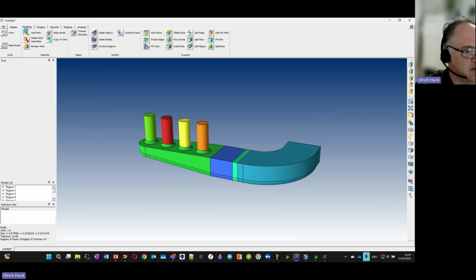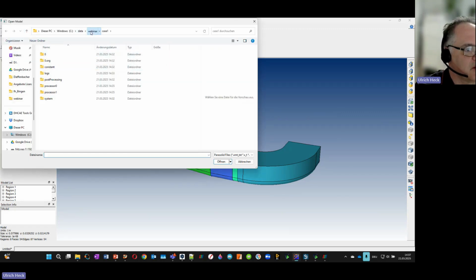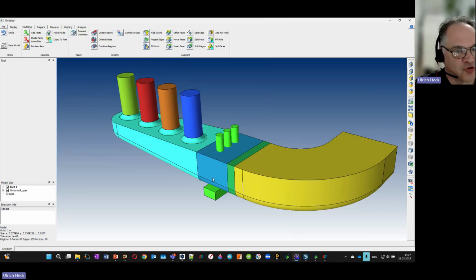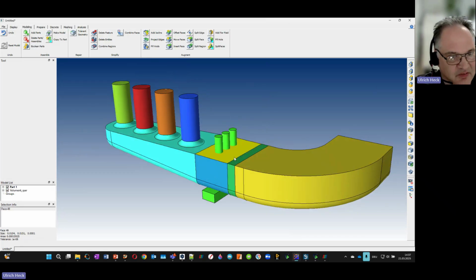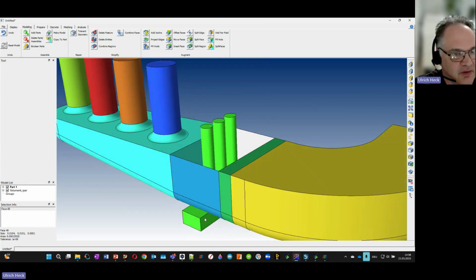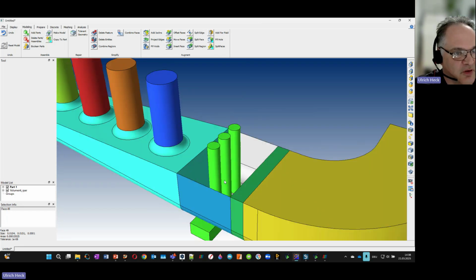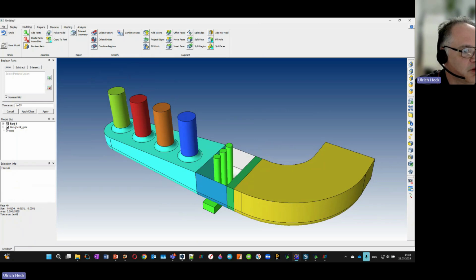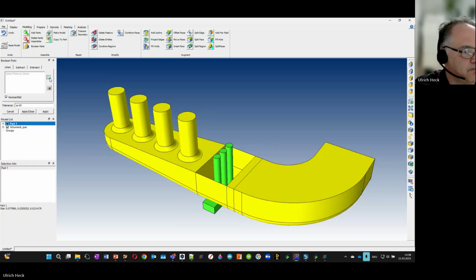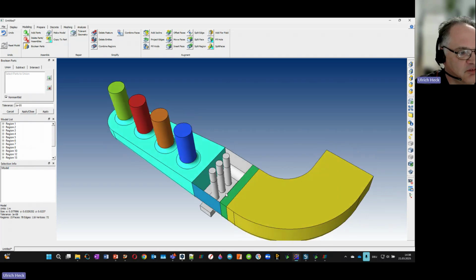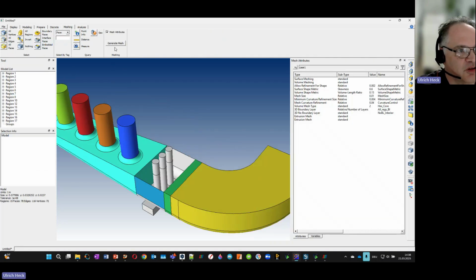And then I can, for example, add a part. And I can add, for example, a heating component. This is my heat element. I add this to my geometry. So when I look at this part, then this part is not really connected to my geometry. The tubes are going completely through the part. And also here, I have two faces. So I have to boolean this part with my model. I click apply, and then the geometry is split. And then I can go directly to meshing again.